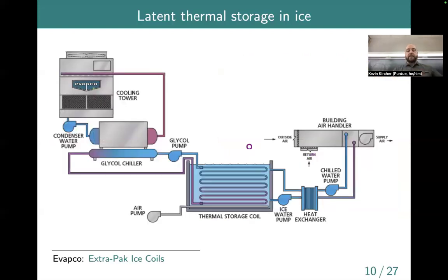So here is a schematic of what that might look like that has all the mechanical equipment in it. So this is the big either swimming pool or ice rink, depending on its phase. And then this is an illustration basically of the heat exchanger coil that goes through the medium. You might have something like glycol that you can make very cold, but still pump around as the sort of coolant that goes into the water here.